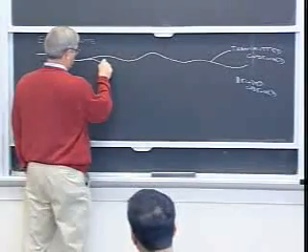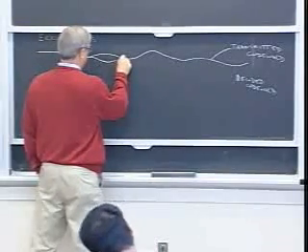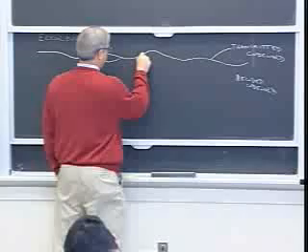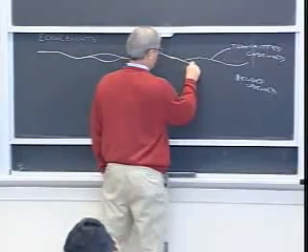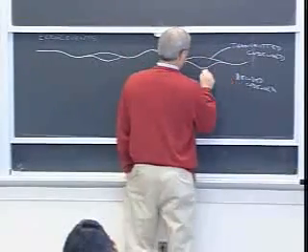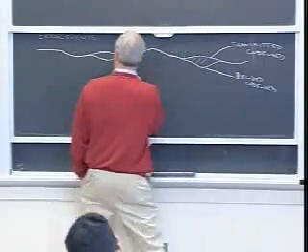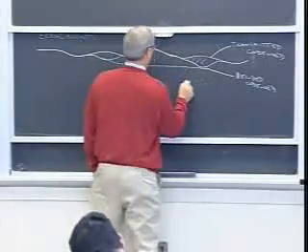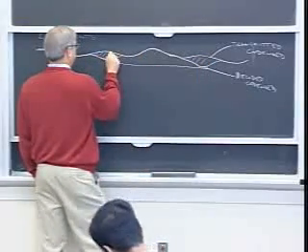And what will the errors look like? They'll look like a branch off through the trellis and then eventually a remerging into the same state. And similarly, you go on longer and you might have another error. Any place where there's a difference, this is called an error event.